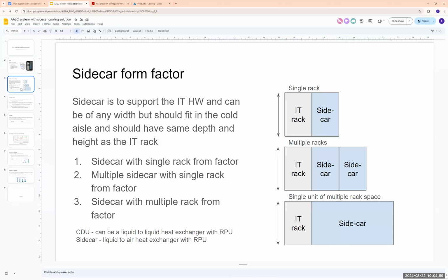We don't have those numbers yet. But that's what goes on the slide. We could probably pick the number for where you transition from a rear door heat exchanger to a sidecar, but then it sounds like the kilowatt chips, which are a year or two away, can still be cooled with the sidecar with single phase coolant. So the driving force to go to a 2-phase coolant, where single phase won't work anymore, might be 5 years away.